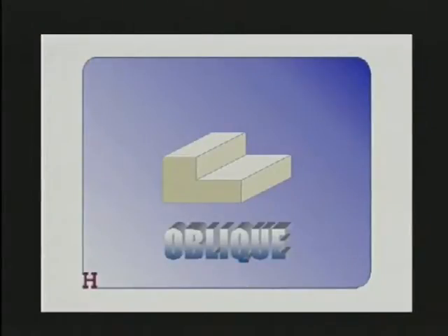However, all 3 of these types of projection, perspective, isometric, and oblique, are inadequate for completely communicating technical information. The problems we get into are when we have things in the views that are hidden away from our sight, or when we need to precisely dimension every feature. So, orthographic projection has been invented.